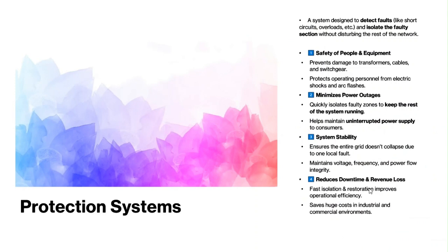And let us understand why it is the most important. The primary reason why protection system is introduced in a substation is to protect either the equipment or the personnel working there. Let us take an example. One 160 MVA transformer will cost something around 2.5 crore, and if we don't use any protection system, then we are allowing it to damage when there will be a fault. Whereas the cost of a protection system could be something around 20 to 25 lakhs.